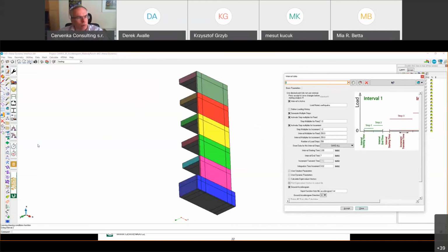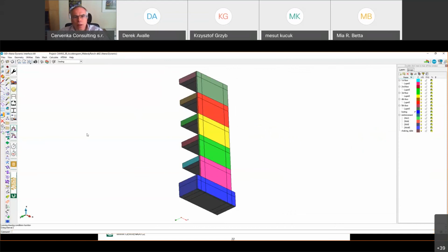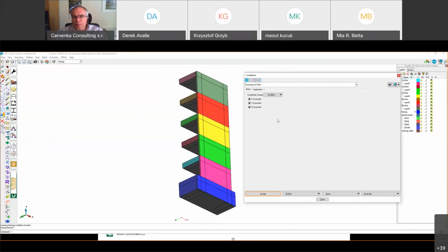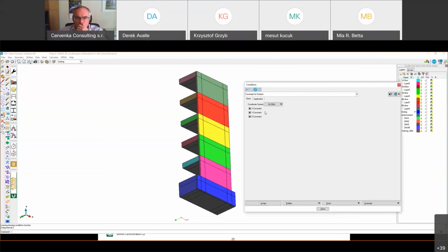The other method is to use the condition from GiD. In these conditions, if you see, one of the conditions is acceleration, for instance. So if you use that condition, you can describe it as a value. And in addition, you have a possibility to define a function. So in this case, you can also provide some time history for these accelerations.